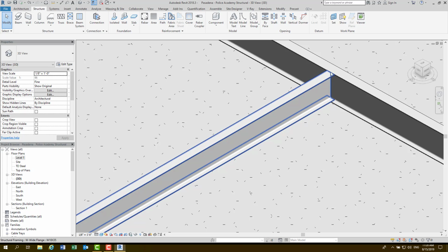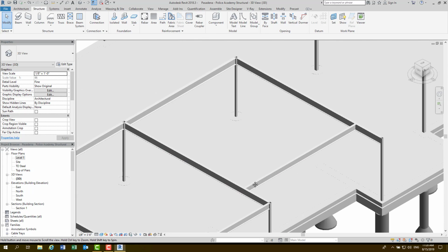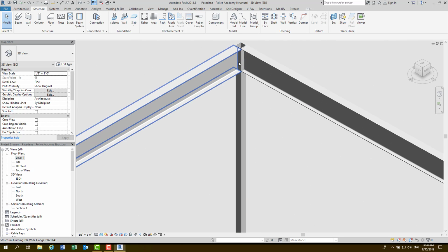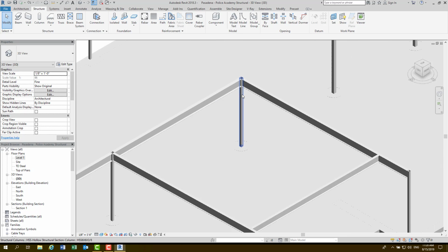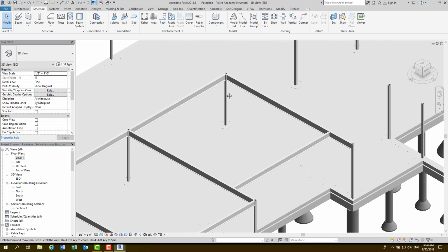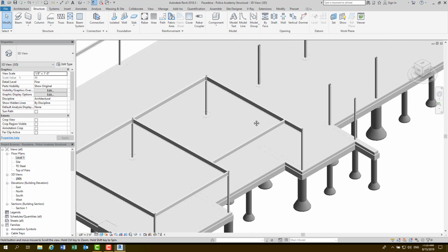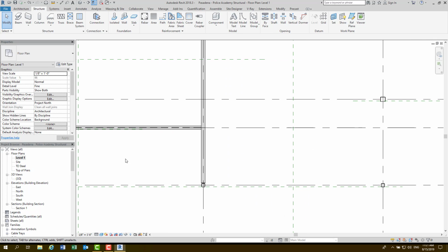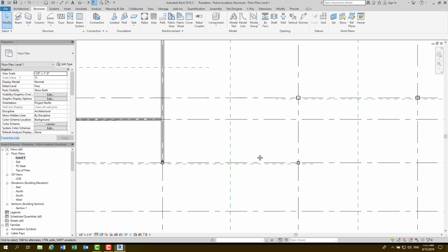Now Revit does have the ability to go in and put these structural connections, with the bolts and everything. It's a little overkill right now for what I'm trying to do. Having that high level of detail doesn't necessarily add anything to the model and for the project. Being able to see where the bolts and the connections are doesn't really do anything, unless you're just trying to make a really realistic model. But then that's going to increase your file size. That's going to increase your computer's ability to compute the information. So, you've got to kind of have some give and take when it comes to your level of detail. You really got to decide what's important and what's not. And I found that those structural connections just aren't typically worth it.